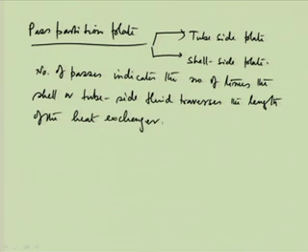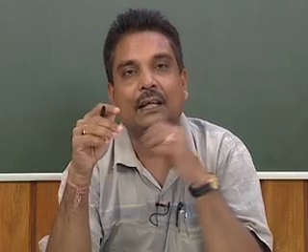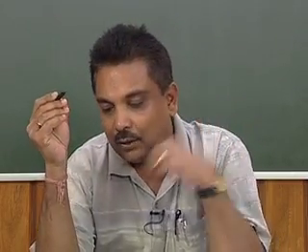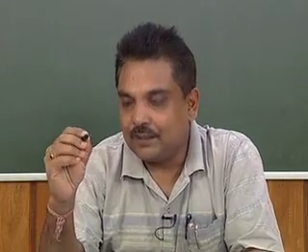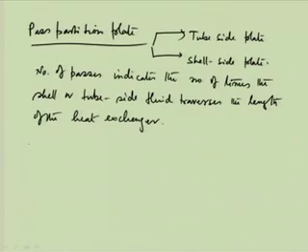Therefore, there are two types of plates, one called shell side plate and one tube side plate. As we understand, the tube side plates will be in the nozzle or in the bonnets, while the shell side plates will be in the shell, throughout the shell. Now, there are different types of shell and tube heat exchangers possible depending on the number of passes.